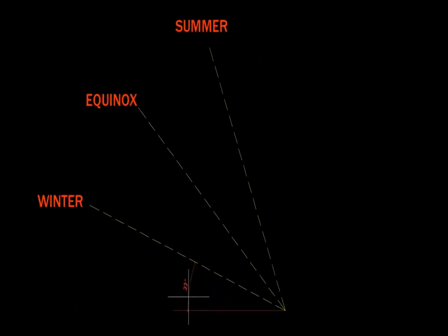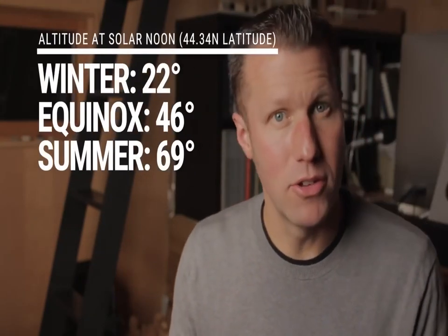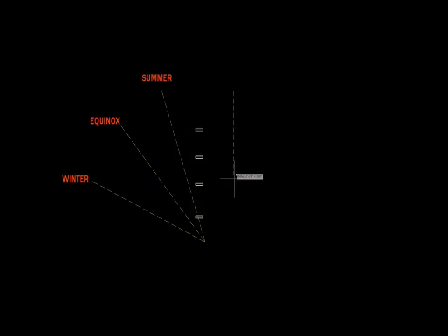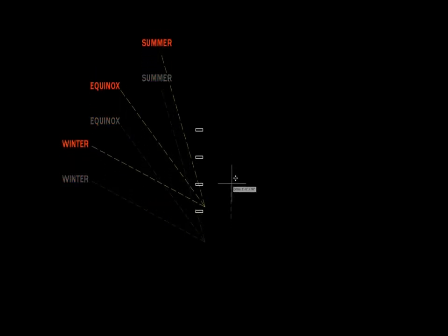Okay, next step is to take these angles and plot these values on your drawing. Remember, the angle is above 0 degrees, which is, for our purposes, the horizon. So naturally, 90 degrees would be straight overhead. So here in Maine, it's something a lot less than 90 degrees. Okay, so these are our values for the important calendar dates. And given these angles, I start with some basic assumptions about my louver design, and then I begin tweaking as necessary to get the intended effect.